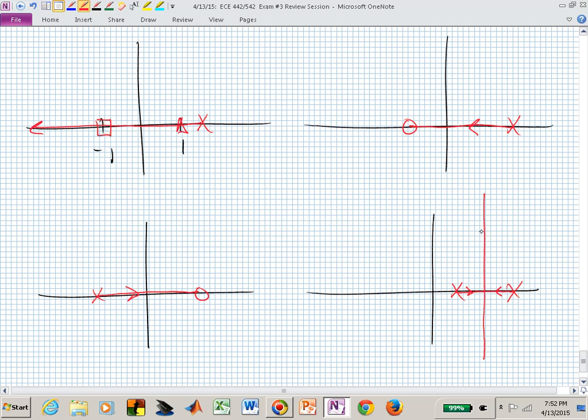And they are not bending. They are going straight up and down at plus and minus 90 degrees. And depending on where the unit circle is, if that rightmost x is inside the unit circle, do you have to worry about stability? If I've given you the location of those poles, could you determine the maximum value of gain for stability?